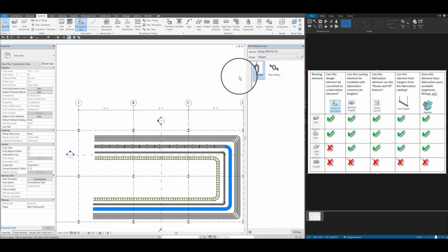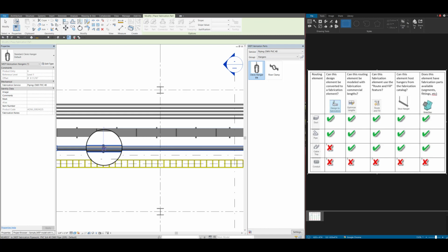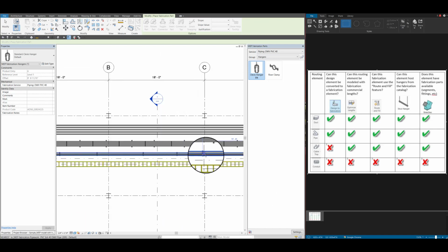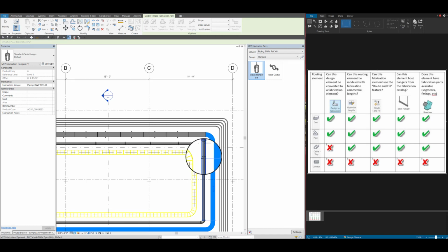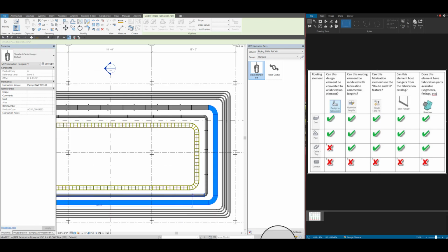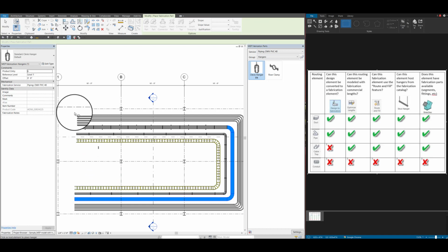After I do that, then I can click on the hanger icon, and as soon as I hover the mouse on the pipe, the hanger recognizes the size and elevation of the pipe, and it also recognizes the nearest structural element, which is the floors. So remember that I put different floors with different elevations. Each of these hangers is going to find the proper location on the roof or slab.